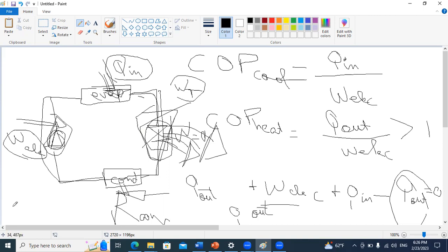So the net work, yes, exactly, is the useful output, and we divide it over the energy that we are putting in, which is Qn, the energy of combustion. Here Q out will not figure in this relation, but we can use it to determine W net, because W net is equal to Qn minus Q out. So like the thermal combustion engine, the output is the work and the input is heat.